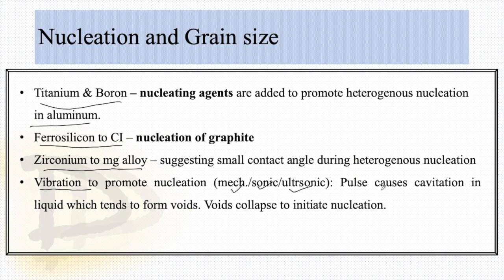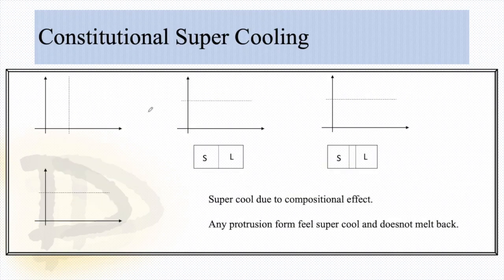The pulse of the vibration causes cavitation in the liquid, which tends to form voids, and due to high pressure, these voids collapse to initiate the nucleation. And for cooling, we must ensure the liquid does not melt back, which can be done using constitutional supercooling.